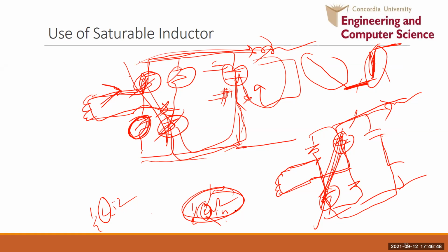So automatically your soft switching range has improved, and when you enter the hard switching region, the storage is already very low, so the switching losses will be less compared to silicon devices.